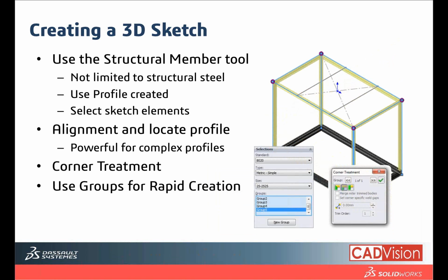In SolidWorks, if you are using the same group, I mean, in one weldment, you can only use one type and size. If you are going to use different types or sizes, you will have to click on the structural members again. So the groups will determine the directions.